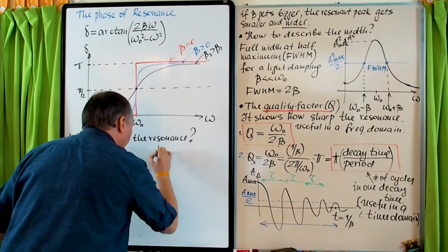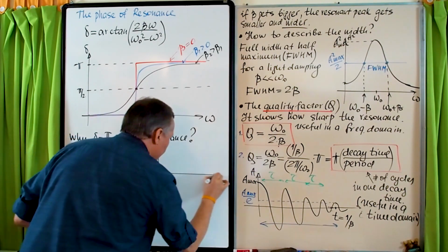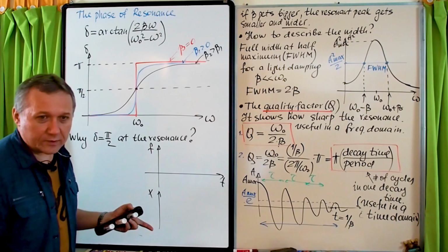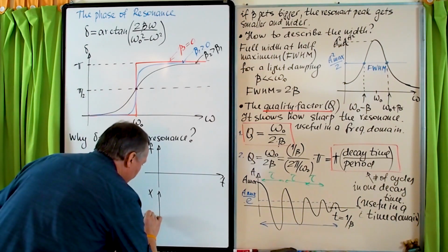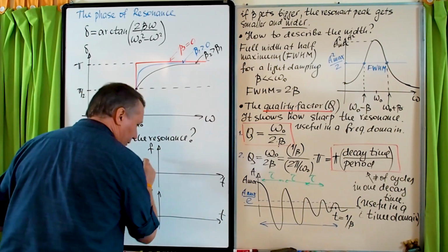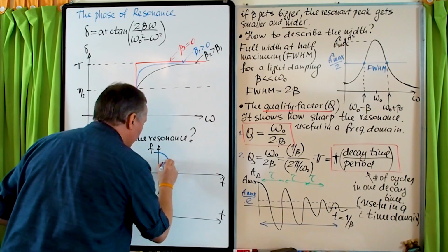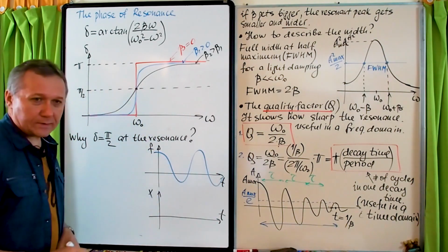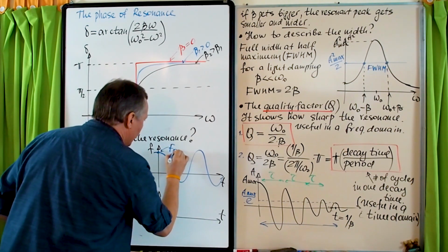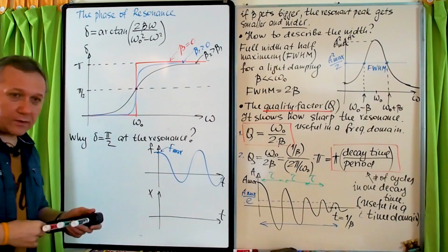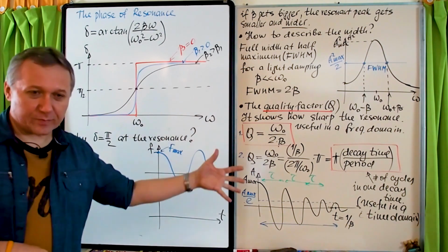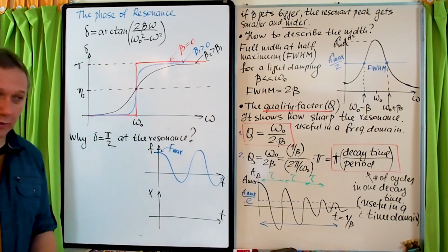All right, so I plot F versus t, and here below x, again, x is the response, a displacement of the system from the equilibrium, x versus t. If I plot this amplitude, I think we use the cosine function, yeah, cosine. Something like this, right? So here, the maximum force. At this point, we have F max, right? And again, the power is force times velocity, right? So at the resonance, force must be maximum, and at the same moment, velocity must be maximum.